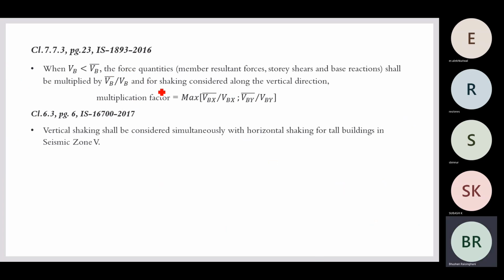And here, importantly, whenever we are defining a response spectrum function, we are giving it a scale factor. So this comes in under the design stage. To design the structure, we are giving the scale factor and we are scaling to the static ratio. We have defined it in X direction, so this has the scaling done in X direction. This is the scaling done in Y direction.